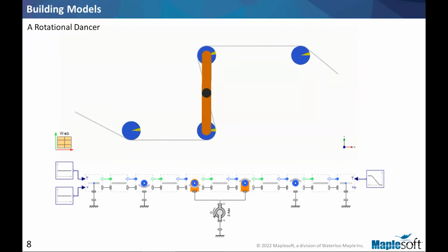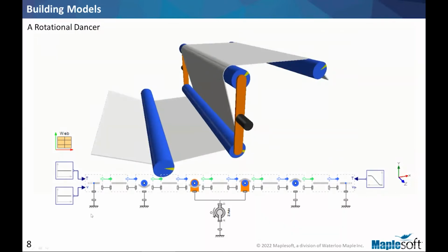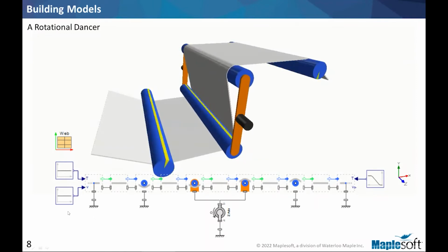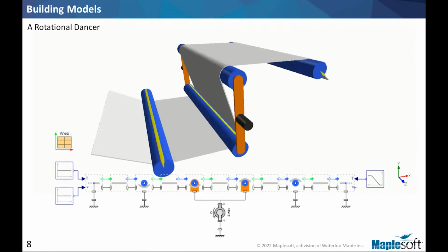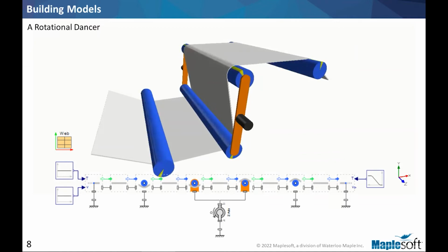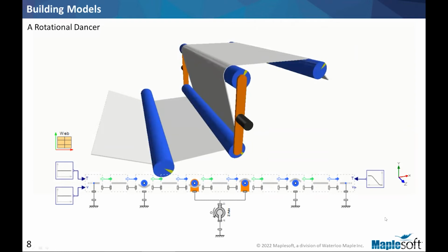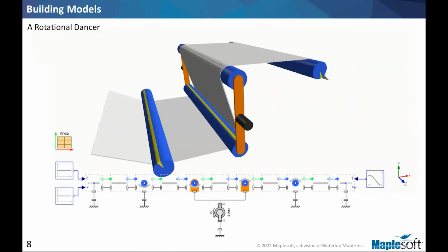There's some other pieces that got added, namely on the left-hand side, you see here on the source, we are using signals. One goes to tension, the other one goes to velocity. For this simulation, we are assuming the upstream tension and velocity are constant. If that's not the case, we obviously can use different types of signals. Similar to what you see on the downstream side, on the other end of this model, we have a sink component. And for that, we are specifying tension.